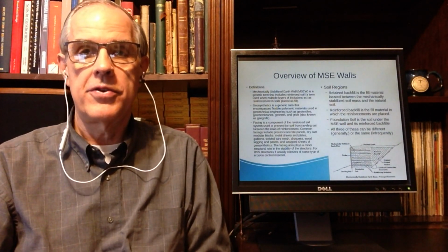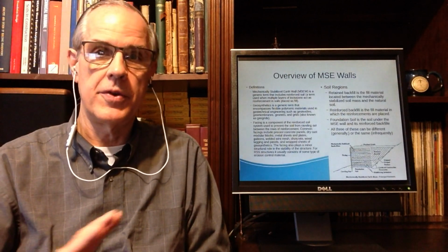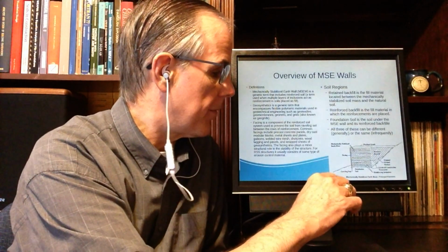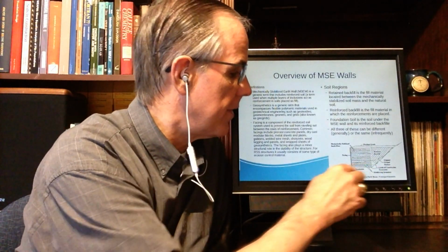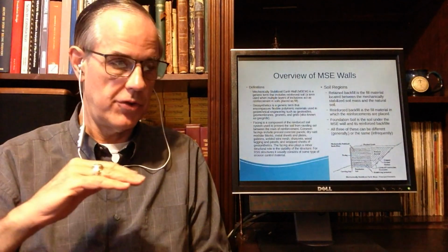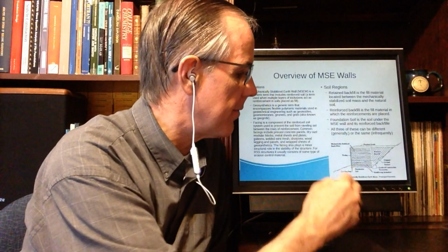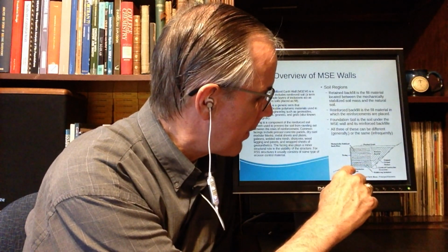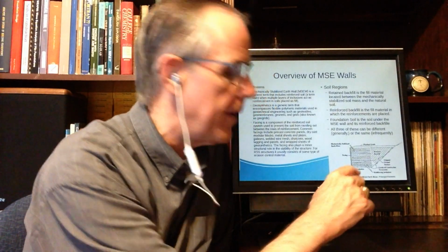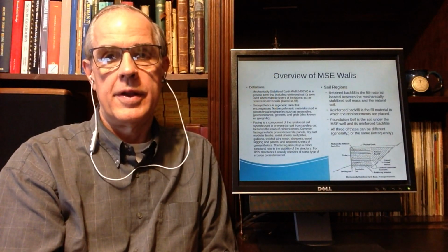Now that foundation soil can be very significant. It obviously influences, as is the case with gravity walls, the friction that you can get along the bottom of it to ensure protection against sliding. It's also important because down here at the bottom they call a leveling pad, or what it amounts to is a continuous footing. At least usually it's a continuous footing